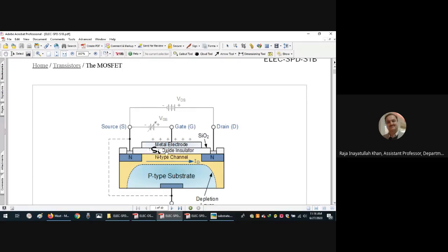So this is normally mica or some insulating material can also be used, but in this case it is silicon oxide. Then upon the silicon oxide layer, this is in microns, remember, it is a very thin layer, as a dielectric, you can call it, or the insulator. And then upon this layer, there is a metal electrode, normally aluminum, mounted. So altogether, what it forms is a metal oxide field effect transistor.